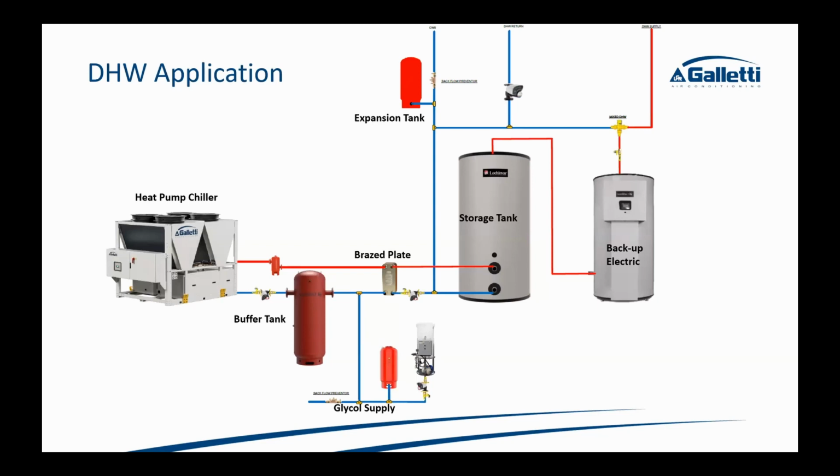We believe, at least our position for any of the domestic heat pump systems where you have a hydronic circuit, is that it's best to just glycol that circuit. In this case, it's a domestic application, so obviously we would have to isolate that. But it also brings up the point that there are some units out there that have a double wall heat exchanger and are rated for potable water.